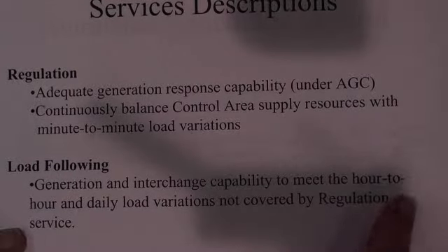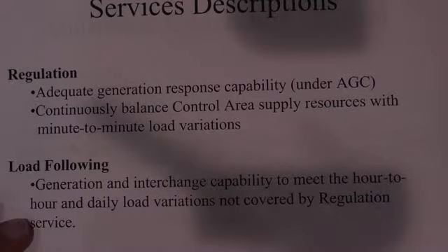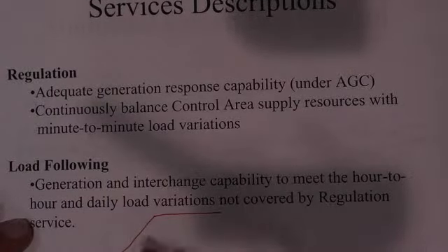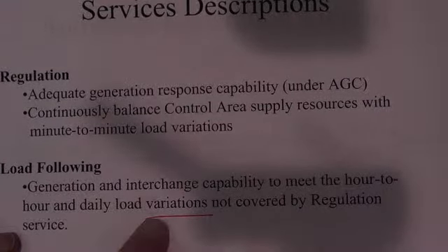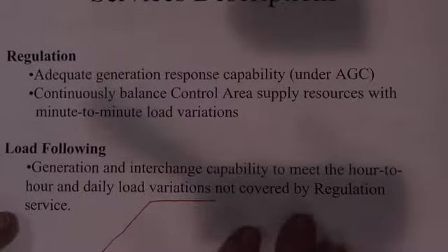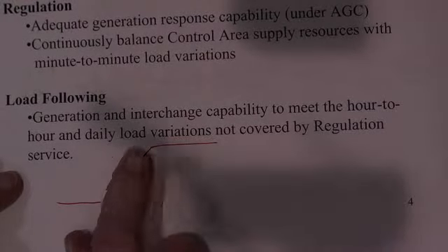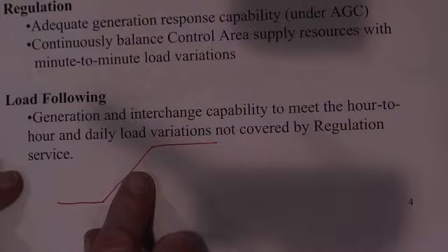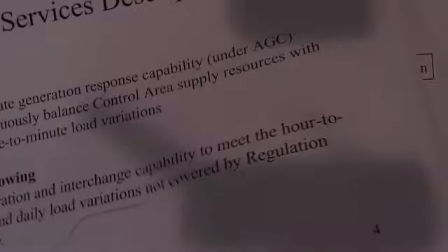So again, if you have a load and every day the load ramps up like this for an hour, then you have to have generators that can follow that. If you don't, and if the load goes up and the generators kind of follow later on, then the frequency is going to be dropping off, because it's going to get that power by slowing everything down. So you've got to have some generators that follow it, load following.